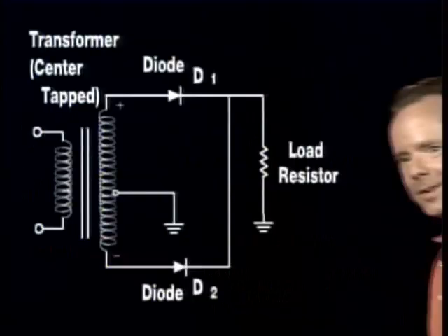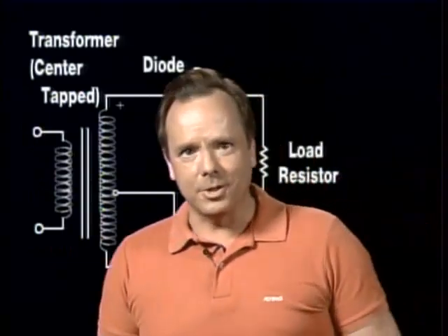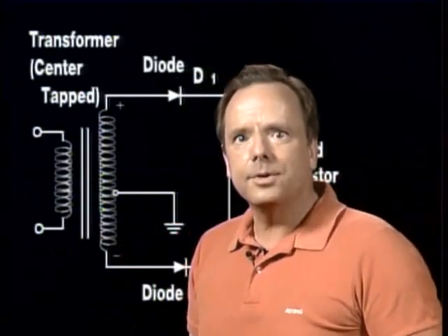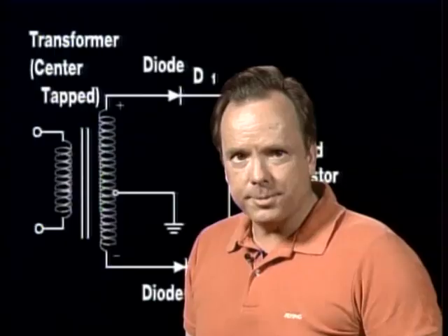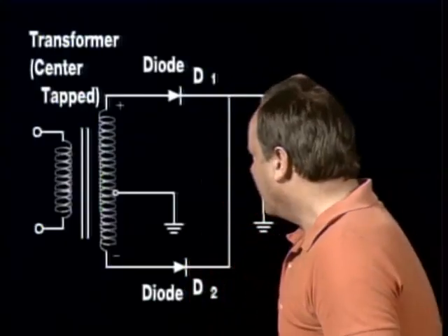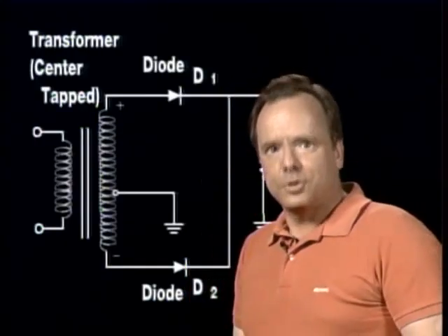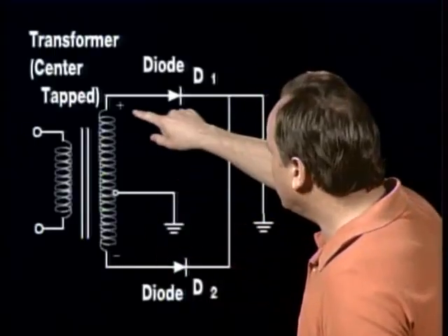Now, this one drawing is going to cover 3 concepts the FAA wants you to know about, and that is diodes, rectifiers, and transformers. Let's talk about diodes first. A diode is basically an electrical check valve. It allows the current to flow in only one direction.